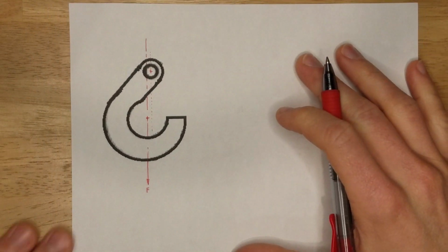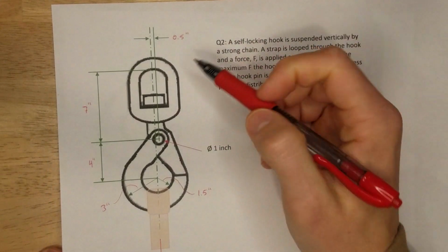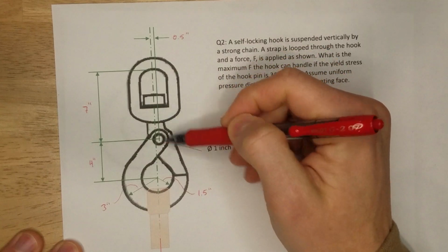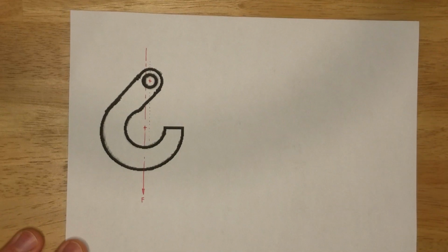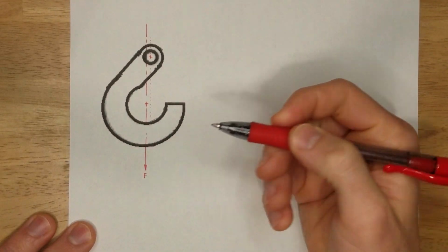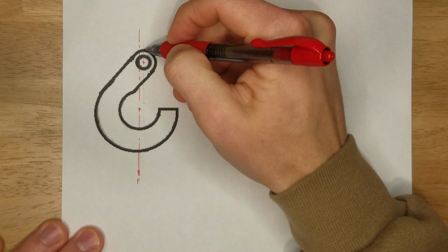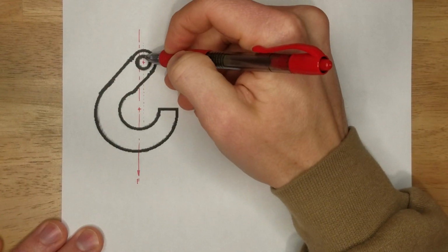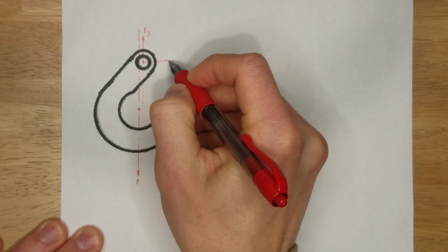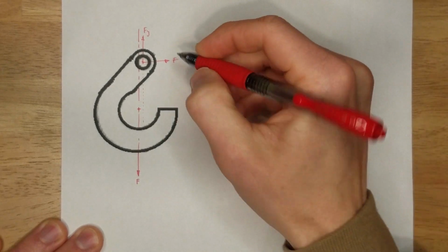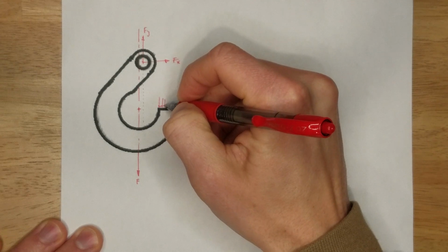Okay. Why did I choose the hook? Because this thing is made up of 3 components. You've got the thimble, or what I call the thimble. You've got the latch and the hook itself. I started with the hook simply because the force is applied to it. You could do it with a latch, it doesn't make a difference, but let's start out with a free body diagram. We've got a pin, so our pin reactions are Fy, Fx, and we've got a uniformly distributed load here.